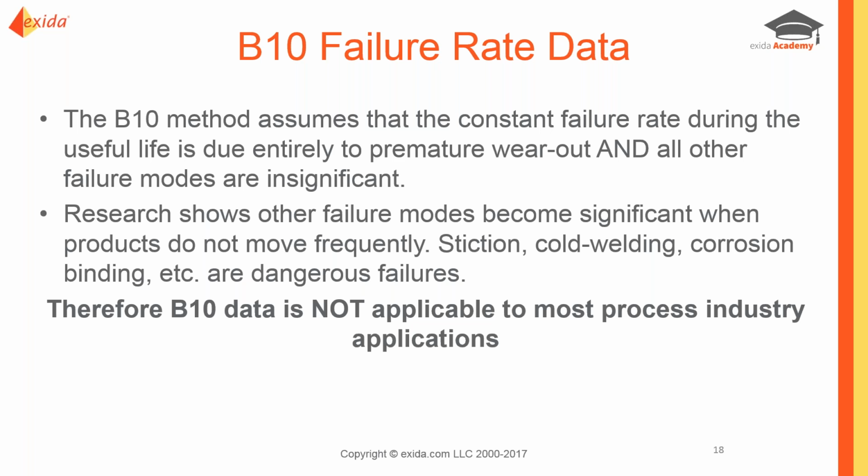So issues like stiction, cold welding, and corrosion, all of these other things that are not wear out failures but functions of being idle, become much more significant, and they are dangerous failures. For that reason, B10 data is generally not applicable in process industry applications. There are occasions where it's appropriate, but for the most part, it's not the best approach.